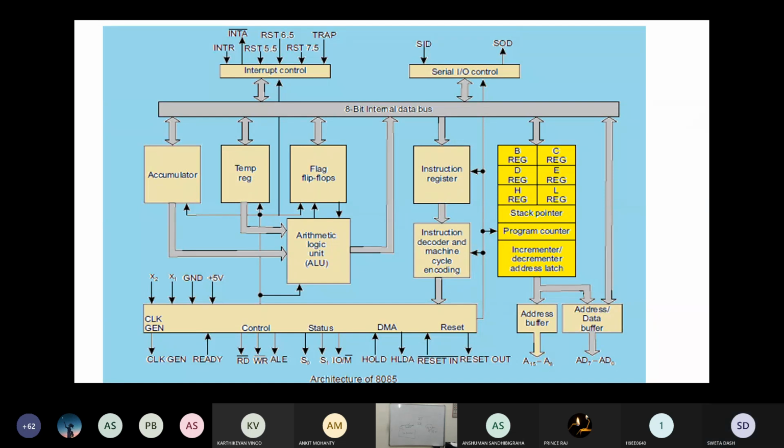Very good. So what are the two select lines doing? I told already we have memory operations or we have IO operations. The two select lines have a choice between these two, IO and memory. IO is always active high. Memory is always active low. Did you see? So the select lines will be selecting either I am doing an operation of IO or I am doing it with the memory. This is how these four are in the same set. Is that clear?